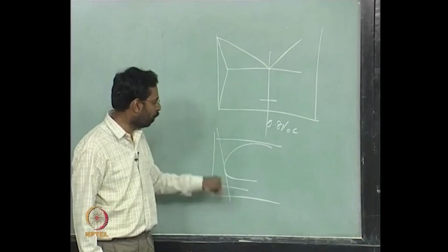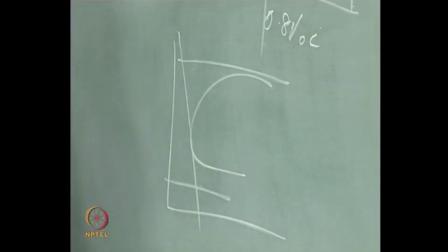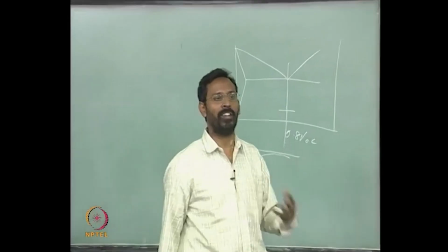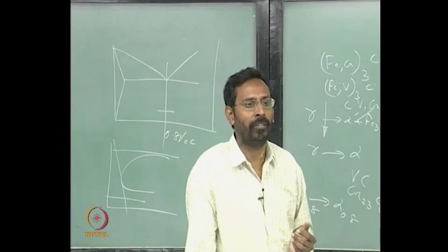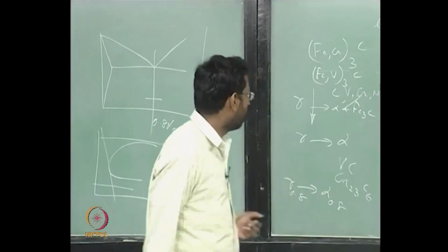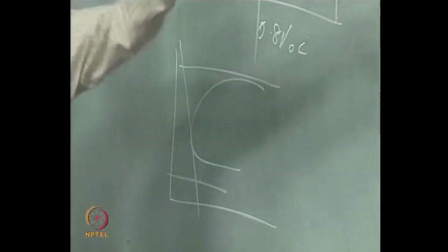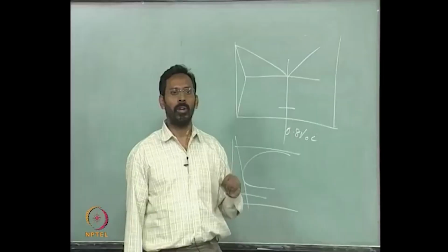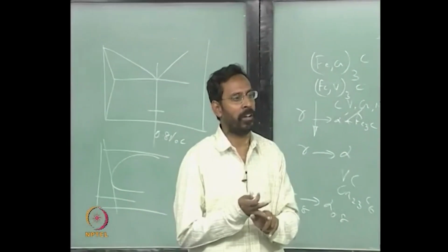You have come to such a low temperature where none of the atoms inside the liquid are able to move, and as a result the liquid gets frozen. That is why we call it a configurationally frozen supercooled liquid. So, this is the basic difference between this and this. So, there is a shear involved in that kind of a transformation. So, any solid to solid transformation has to occur either by diffusion or by shear.